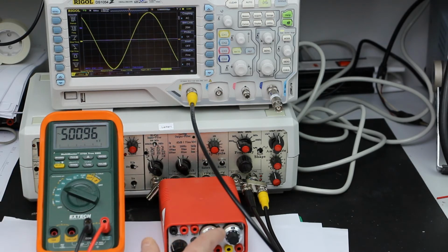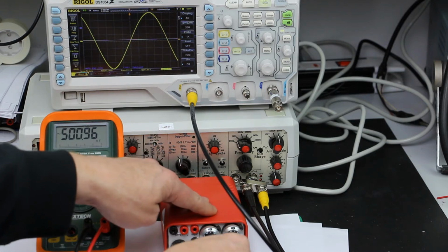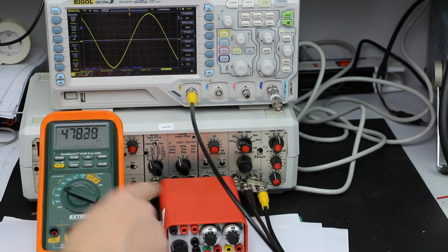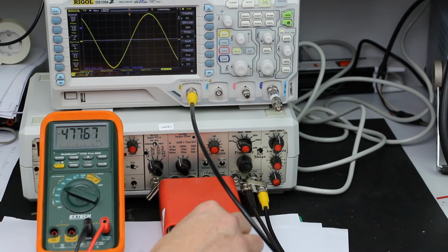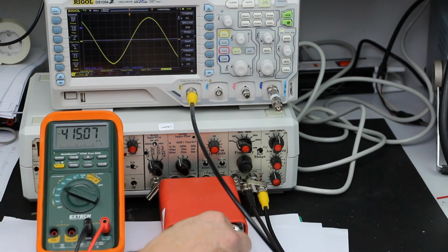I'm only using the 1K trim pot, the 10-turn trim pot, and at the moment I have not connected it, and it is set to the highest resistance of 1K. And now I'll connect it, and you see that already this 1K load slightly dropped the voltage, and now we'll try to find where we get on the oscilloscope to 2 divisions peak and more accurately on the multimeter to 250 millivolts.